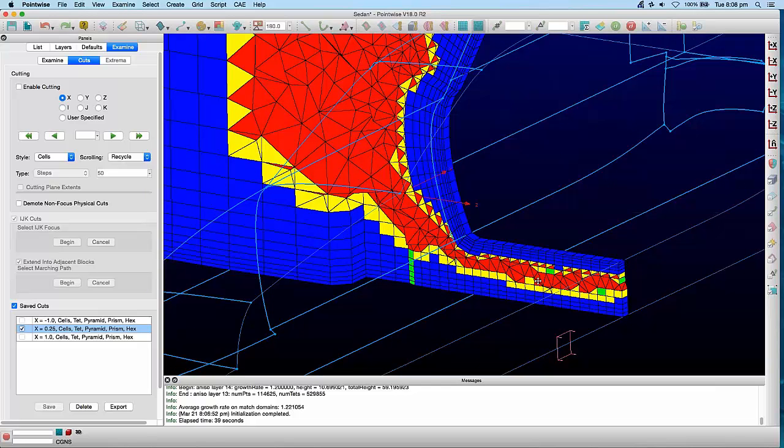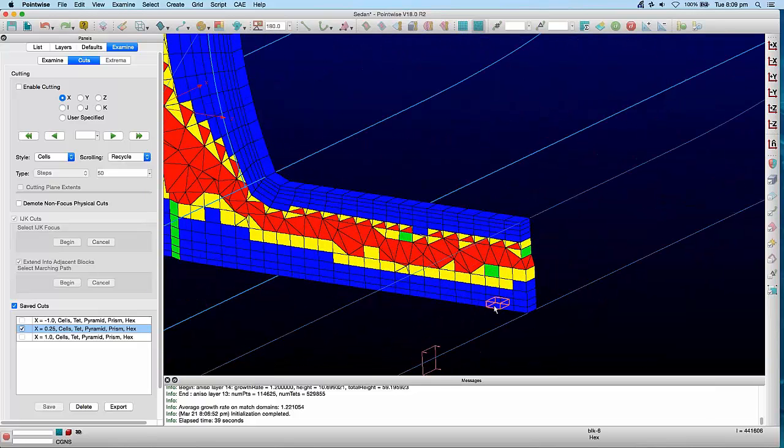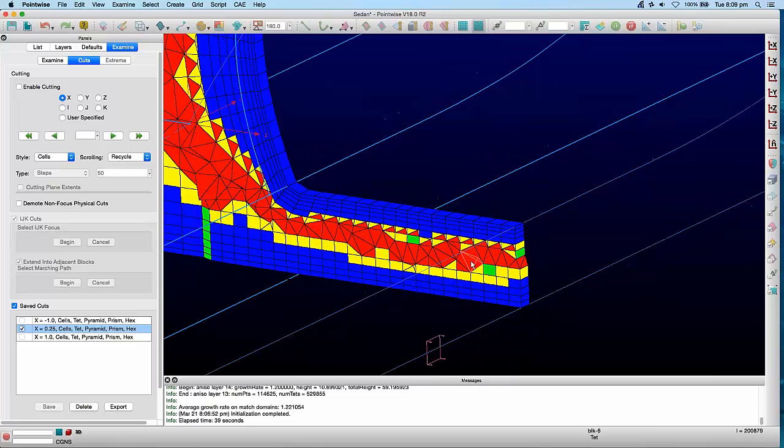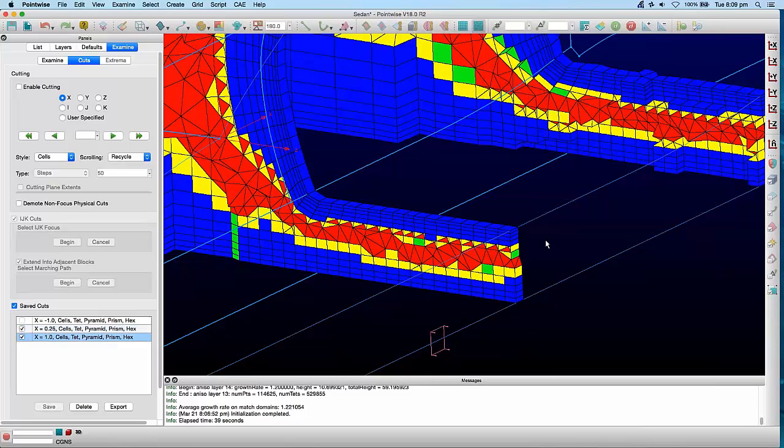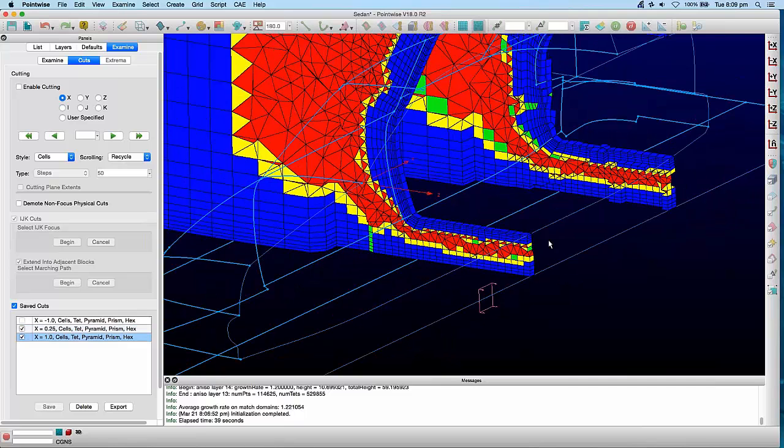If you look down at that floor mesh, it'll be really handy, especially if there's anyone out there who's trying to validate wind tunnel results or replicate wind tunnel results in CFD. You want to be able to get a really good resolution of the boundary layer in the lead-up if you're not using moving ground wind tunnels.